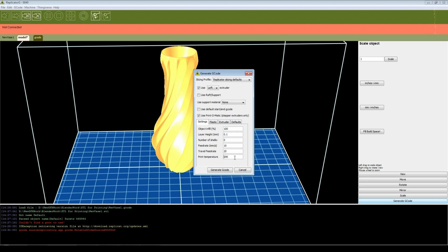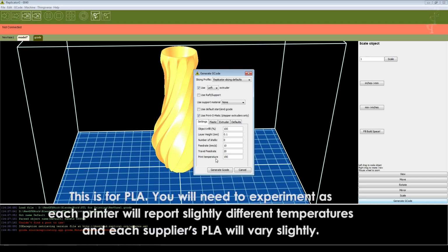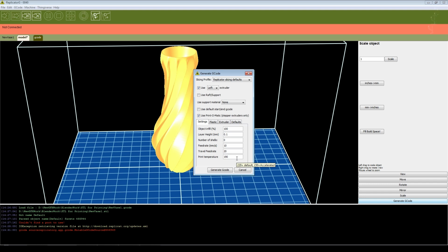And it melts at a lower temperature, so if you left a piece of material created from PLA in a hot car, it wouldn't necessarily completely melt, but it would sag basically. But that said, it's an easier material to print in. So typically you print between 190 and about 215 degrees C. Exactly what temperature depends on how fast you want to go, because obviously the higher the temperature, the less viscous the material is, and therefore you can squirt it out of the printhead more quickly. But there are drawbacks as well.